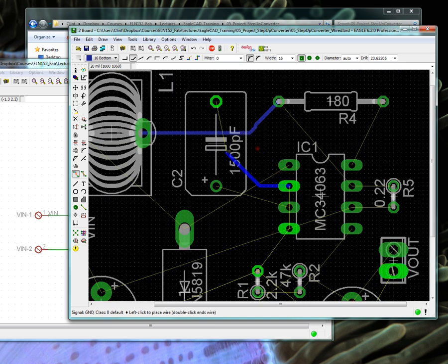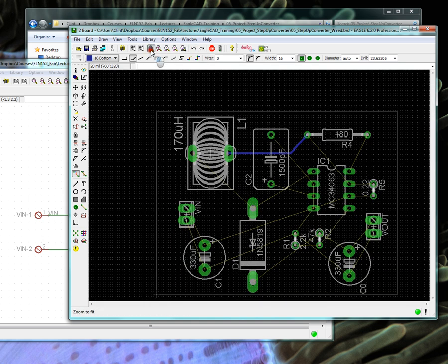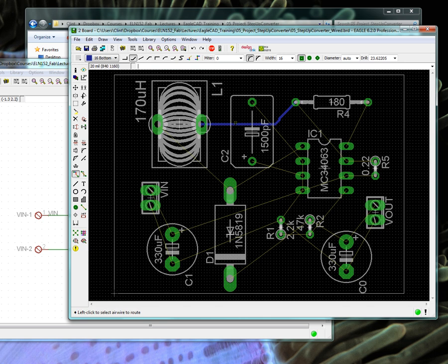So we can just route this thing, or you can auto route it. If there's some important ones that you would really like to have taken care of, then you can manually route those. So if you want to unroute something, you hit this unroute button and it'll unroute it. You can't delete them. If you try to delete a trace, it'll give you a warning.